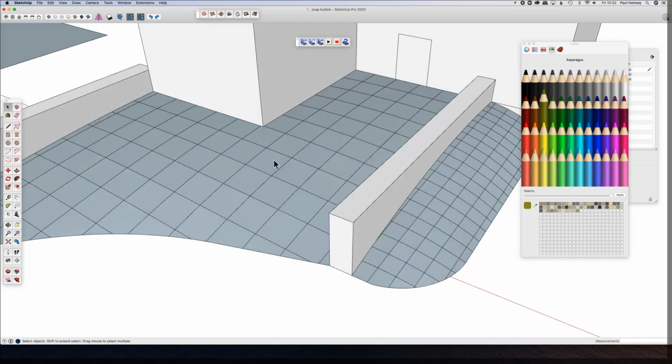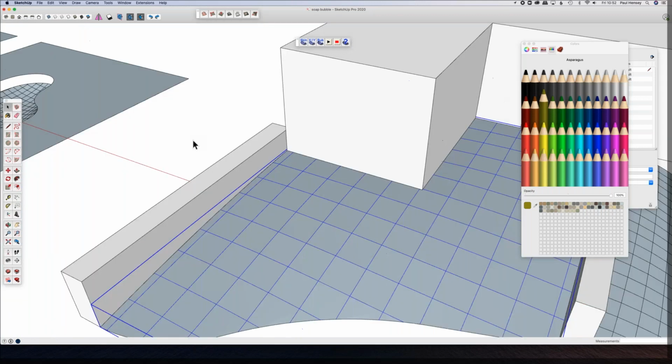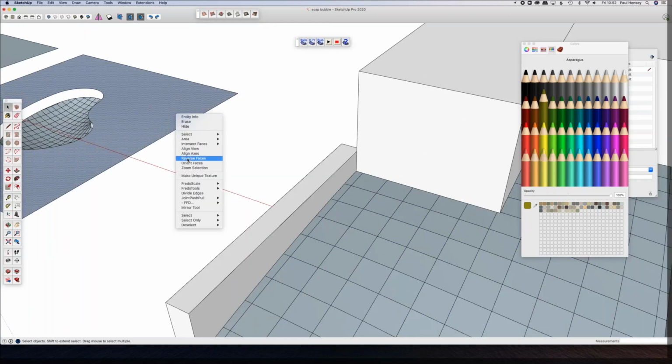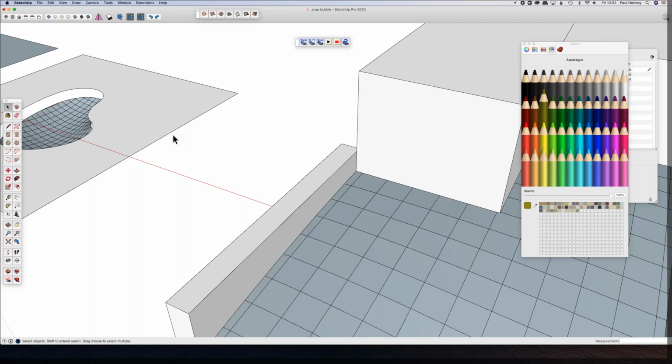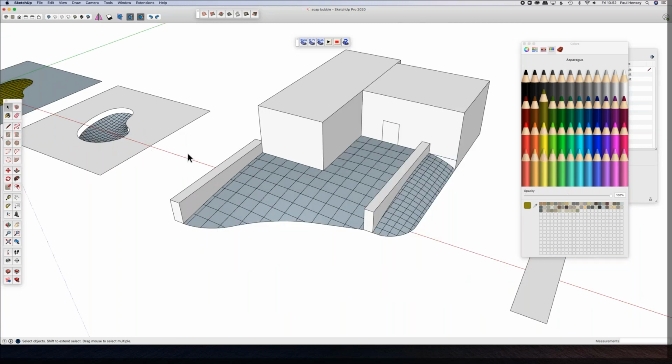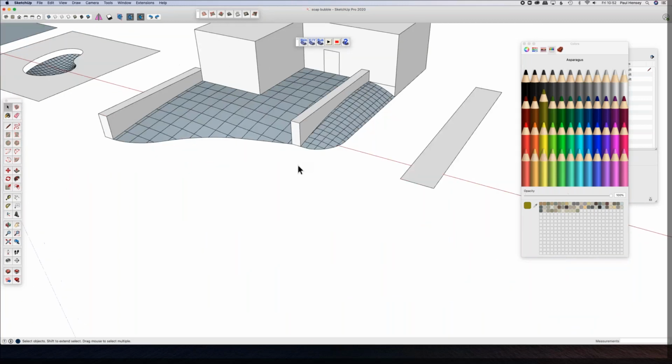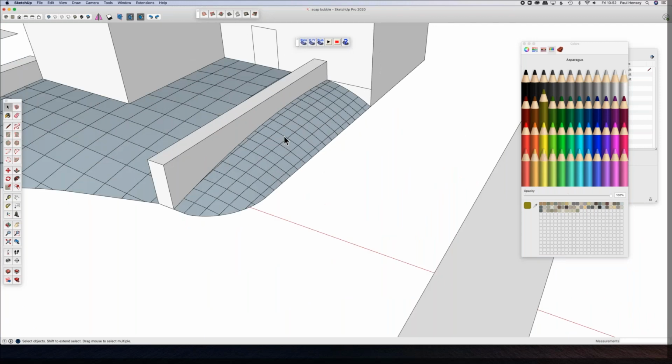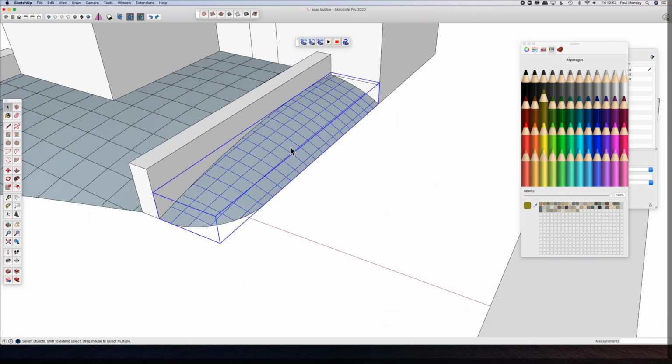I mentioned yesterday that sometimes you end up with these different colors. This surface here is gray. If I reverse it, it's white. And it doesn't usually have a consequence for basic modeling, but here it does, because the blue face is usually the interior or the down face. So that's why I'm having to type in minus. If that had been white, I would be typing in a positive.